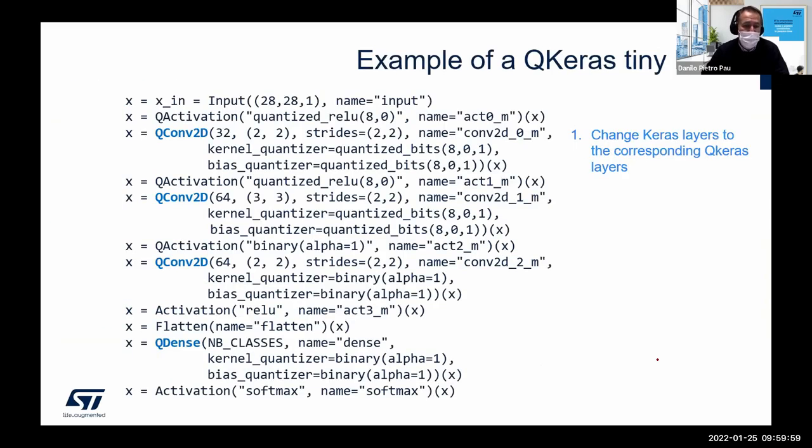This is a ConvNet pipeline, quite trivial. First of all, to become a QKeras pipeline, I needed to introduce quantized convolutions and quantized dense layers, as a quick example. Then I need to quantize the weights. In this case, I am introducing fractional arithmetic, which means the format QM.N.